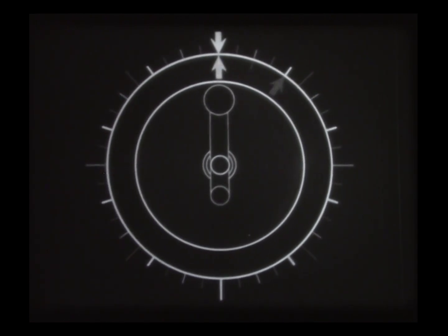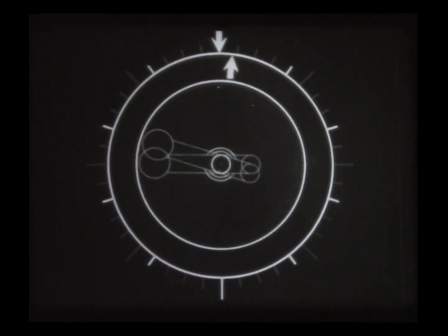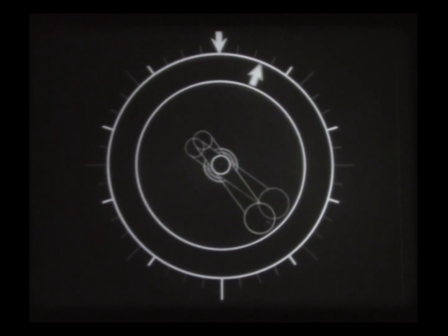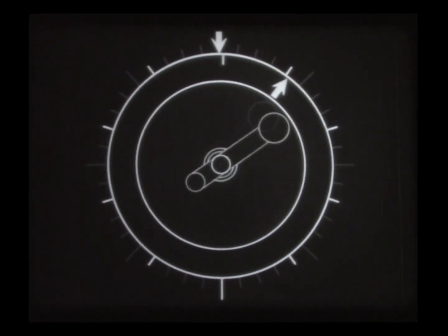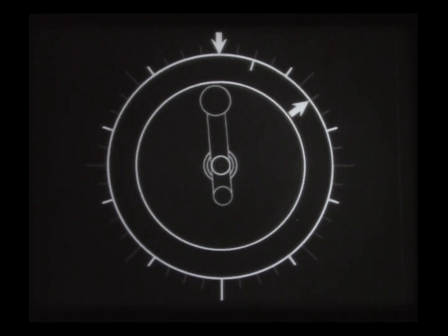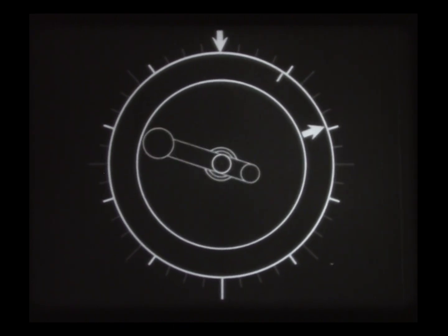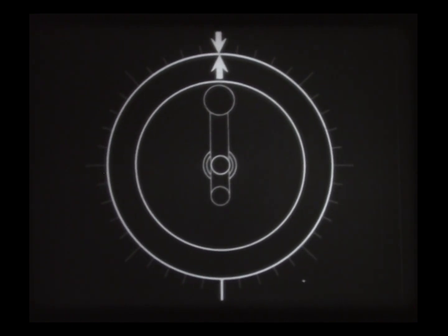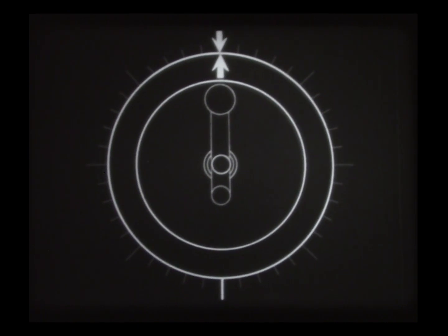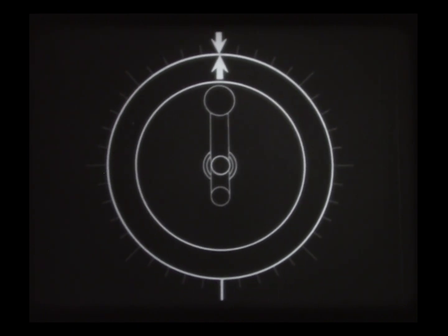If 10 cuts were wanted, 4 full turns of the crank would move the work 4/40ths or 1/10th of a complete revolution, locating each of the 10 cuts. 8, 5, 4, or 2 cuts could be located just as easily, because they too can be divided equally into 40.